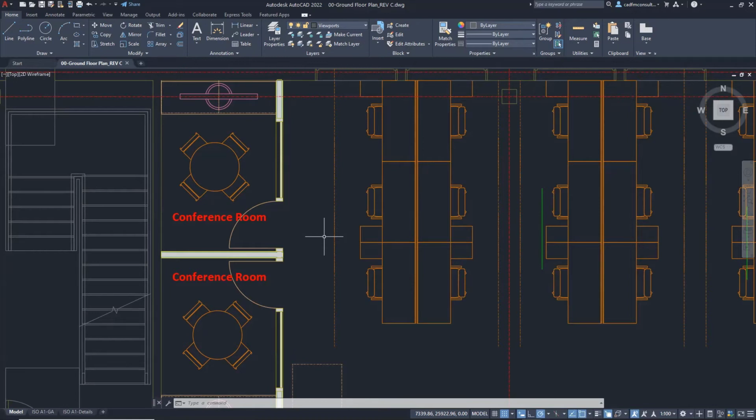So if you've got a whole load of block libraries in AutoCAD, you can put those into the same OneDrive or Google Drive folder, and things like the web app and the mobile app will pick that up. And you've also got XREF support now available on both the web app and the mobile app as well. And the block support is fantastic because that block library can be stored in the cloud and used anywhere.